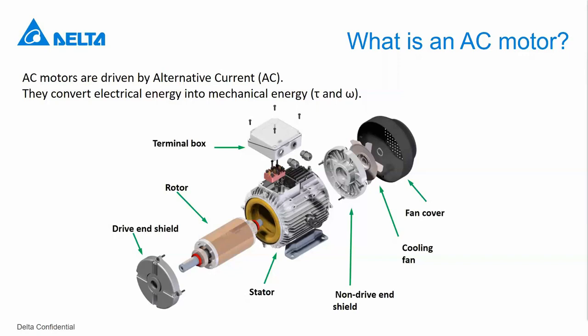The speed of the rotor is proportional to the frequency that it is supplied with, so a higher frequency will result in a higher speed. The torque developed by the motor is proportional to the current going through it. So in most cases, if you have a higher torque applied to the motor, you will see a higher current.